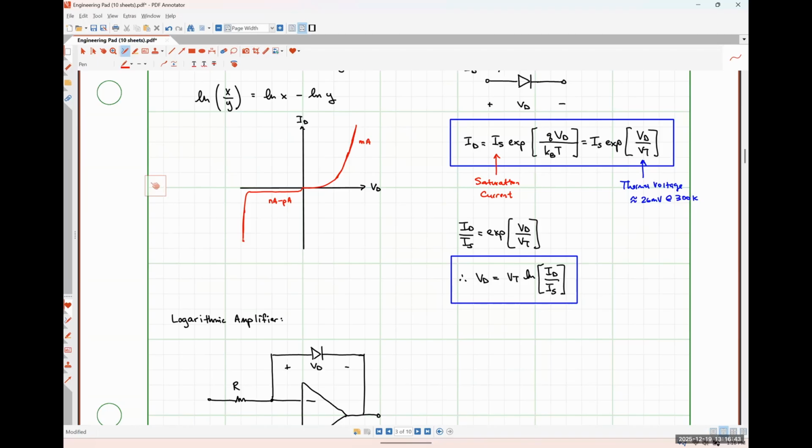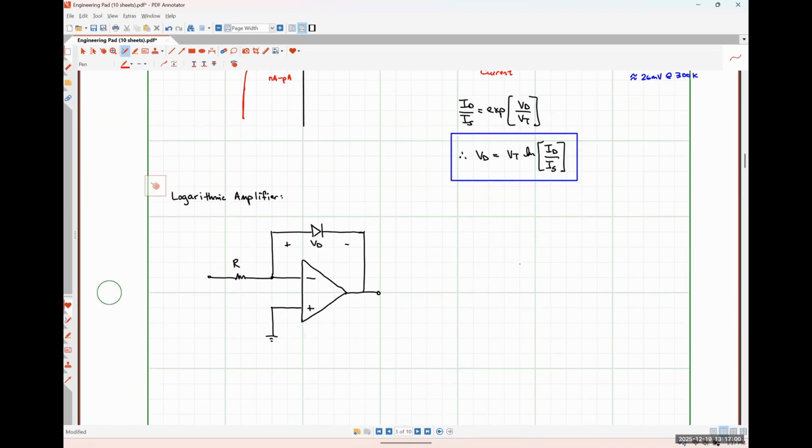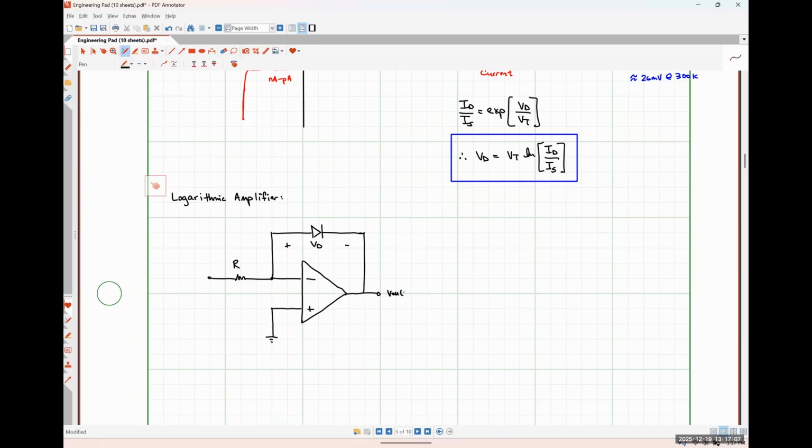Yeah. So the flyback diodes were put in place to only allow current to flow in one direction through the circuit so that it couldn't travel the other way and burn your transistor out. Like I said, it's a unidirectional valve for current flow. Okay. So, like for flyback, is that the same thing like old teams, like flyback? I honestly don't know. Probably the same thing. I mean, a flyback diode is a flyback diode.